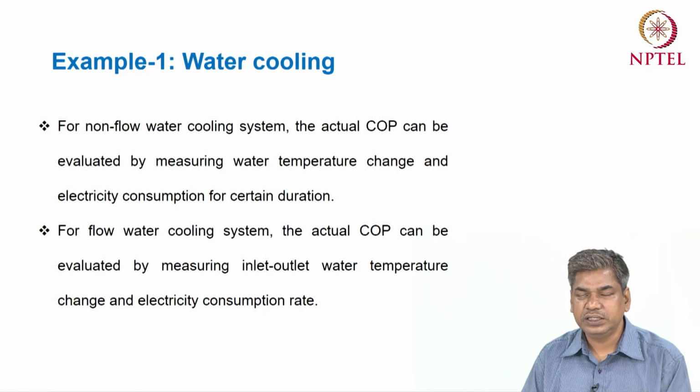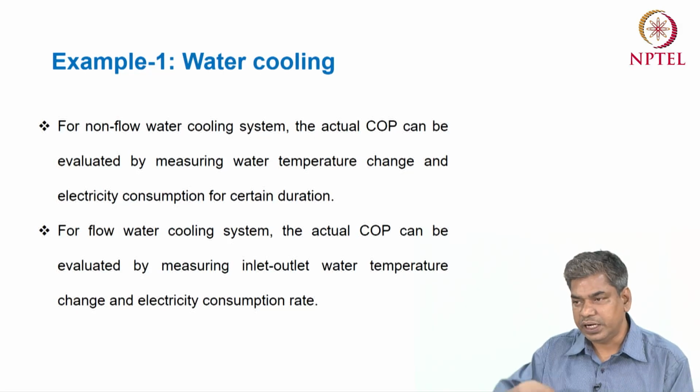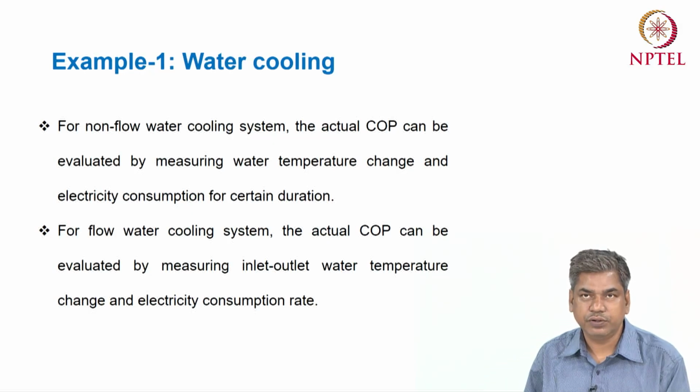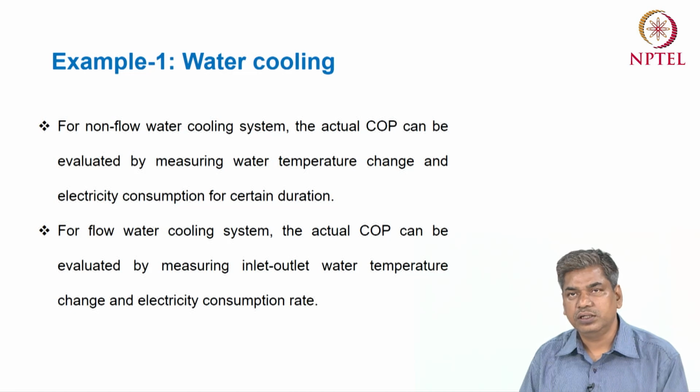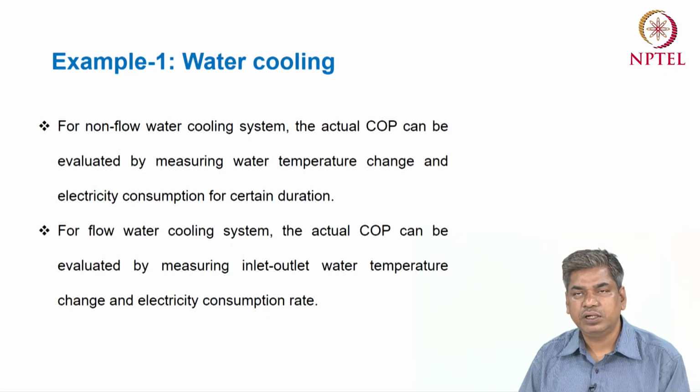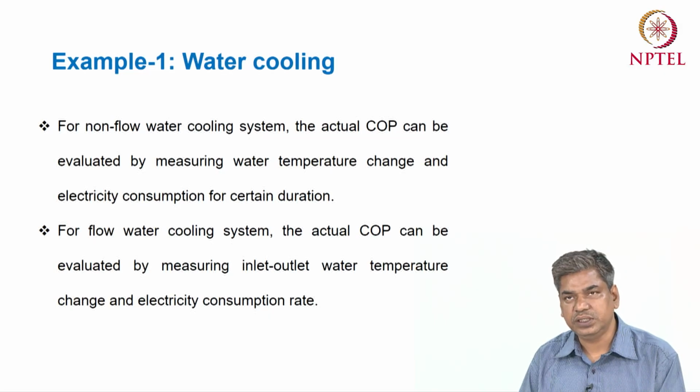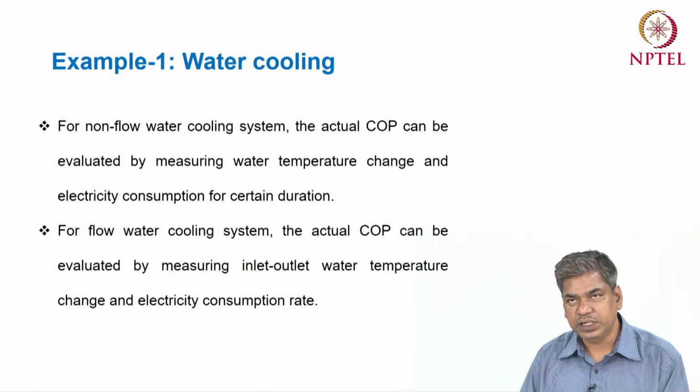In this case, the evaporator coil is immersed inside a container, and that container holds the water, which is being cooled. That is the basic construction of a household water cooler. If you want to estimate the performance of this system, you can make the measurement this way. Before starting the system, you measure the initial water temperature and the initial electricity reading.